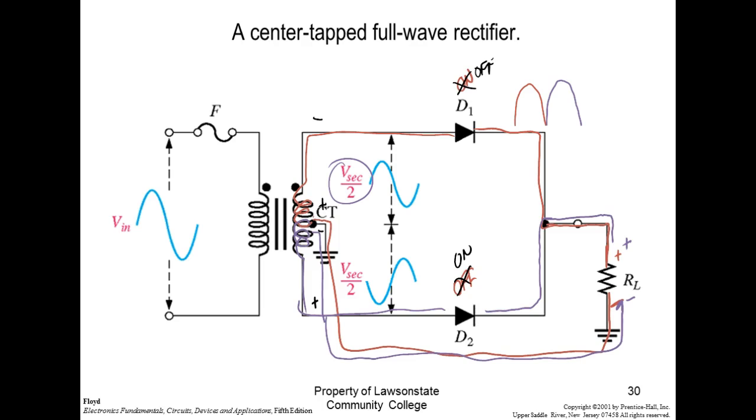So it means that I've got a 12.6 volt center tap transformer up here. And this is the mistake everybody makes. Not everybody. Somebody in this class is going to do this. Somebody in this class is going to do that. So if it's a 12 volt center tap transformer, what we give you is this entire voltage right here, that 12.6 volts. But we're only using 1/2 of the transformer at a time. So that's all the way across here. So what is the voltage relative to the center tap? Well, the voltage relative to the center tap, this would be 6.3. This right here would be 6.3.